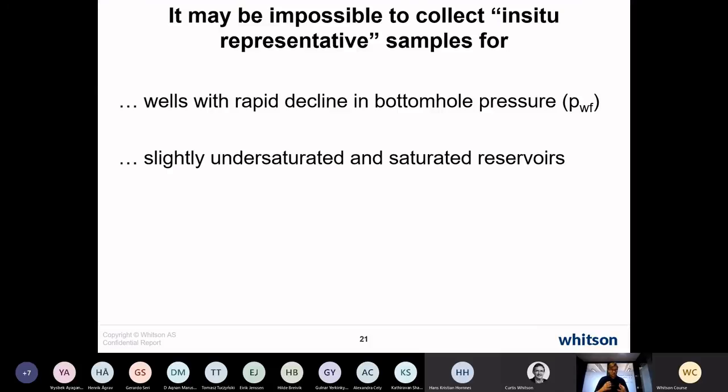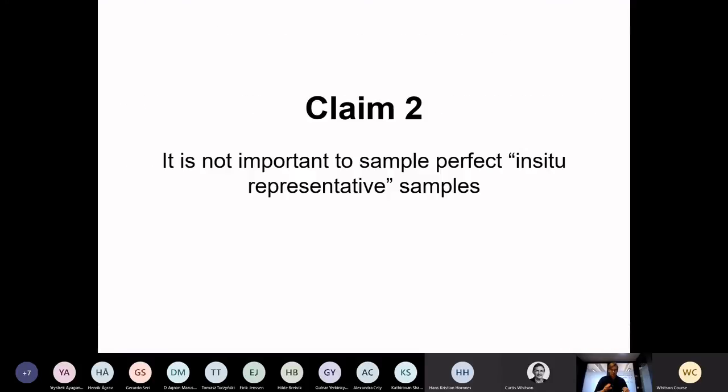So what you produce is not in situ representative, but it is most likely reservoir representative if it's not something very highly contaminated that you're producing back, or that you've injected. For instance, in some unconventional wells, you actually use nitrogen to inject when you complete the well and you produce back a stream full of nitrogen that's not there in situ. So some corner cases like that.